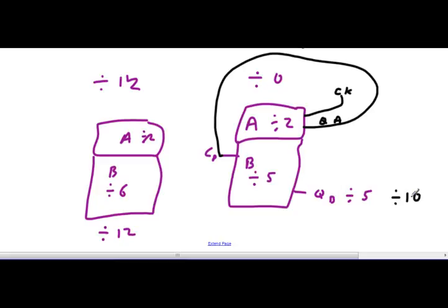So in 7492, when you're getting the extra 4 to multiply, gets 40, and you're running it clock pulse A to clock pulse B, you're getting 12 there? Yes. If I come in clock pulse A and I take QA and send it into clock pulse B, then I've already done a divide by 2.